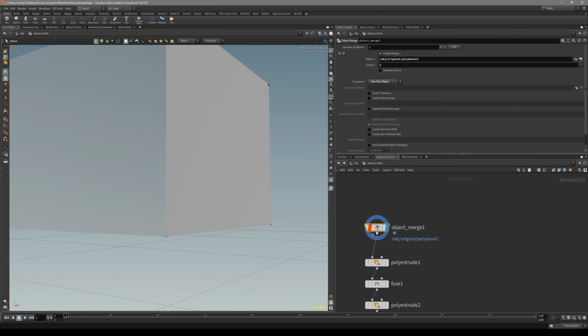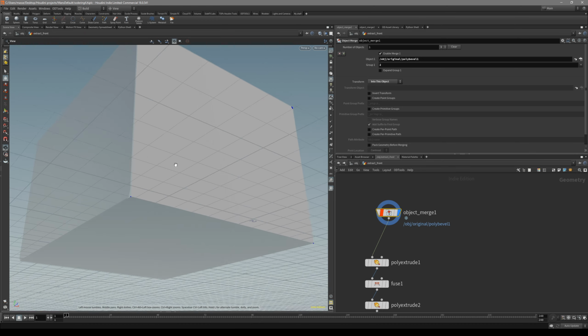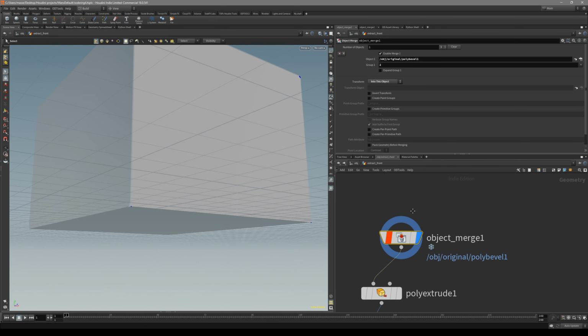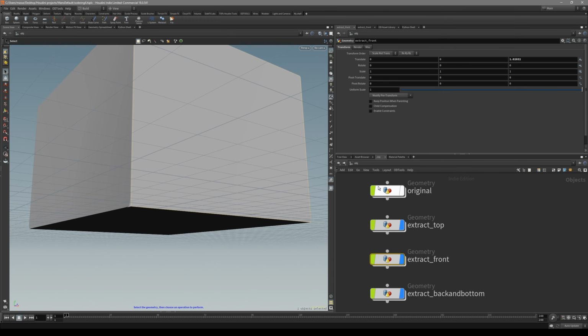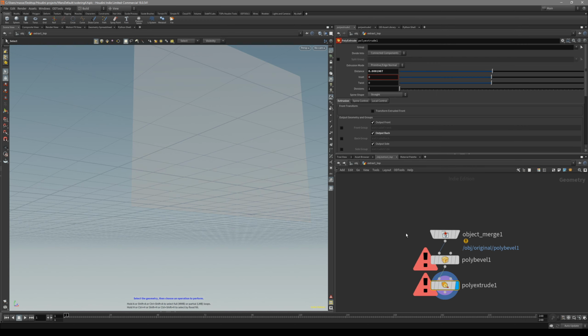So for me, it's a hotkey Alt F4, F8. So what we are basically doing, we are freezing this incoming geometry. So now, if you change the outgoing geometry there, it's not going to change. It basically has frozen everything that comes inside it. And this is like a standalone node right now. So you can even take this geometry and let's say delete it.